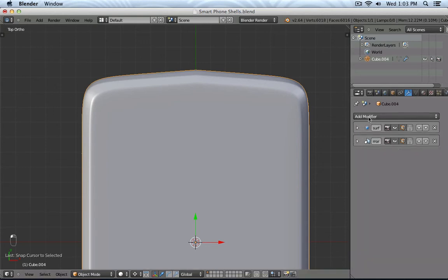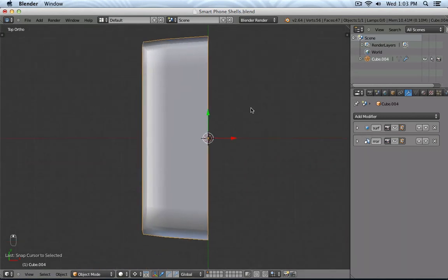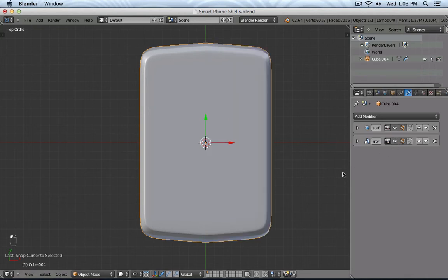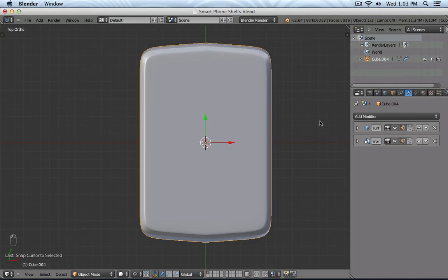Well, if we go back to the modifier tab, you will see that we have a specific order. So we have this object, and that object we apply a subdivision surface modifier to, and then this half we flip over. So this sharp point here, of course, will be flipped over, but no, I would like to have something that is similar to the symmetry tangency. So like in Alias, it's called implied tangency or implied curvature.